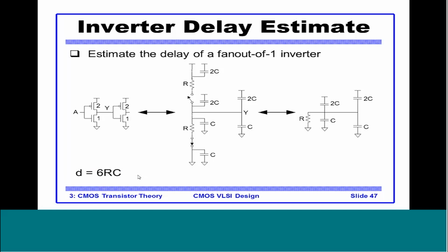So let's say we are making a complex gate. There can be multiple ways of designing that gate using some logic families. Now we can estimate how much delay that gate will take. The gross area we will know by the transistor count, and the delay we can estimate on paper using this RC delay technique.